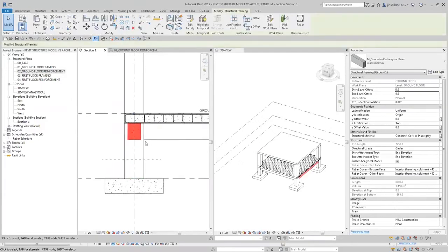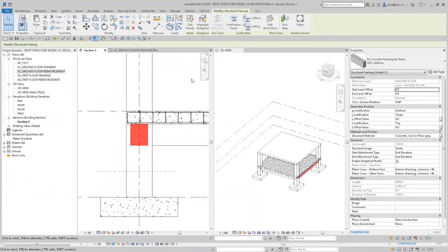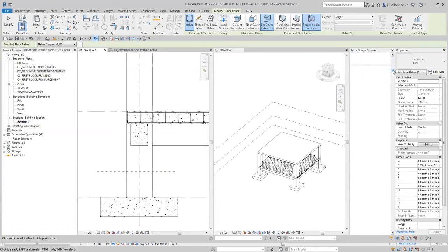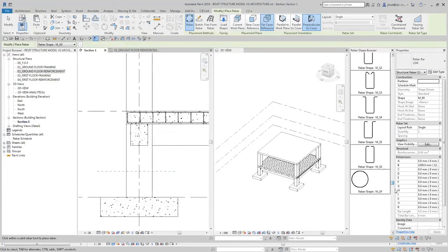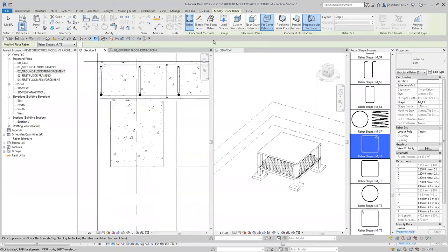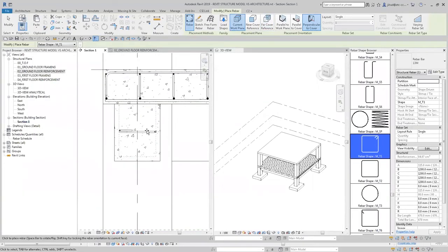If we now decide to place iron in this element, we click on the rebar as illustrated, and a new pop-up window will appear, either on the right, or on the left of the screen, with various iron options to choose from. As we can notice, we have various default rebars to choose from. And by clicking on this one in order to design a new one, using Revit's tools as demonstrated here, with explanation pop-ups that help clarify the ways to do it.